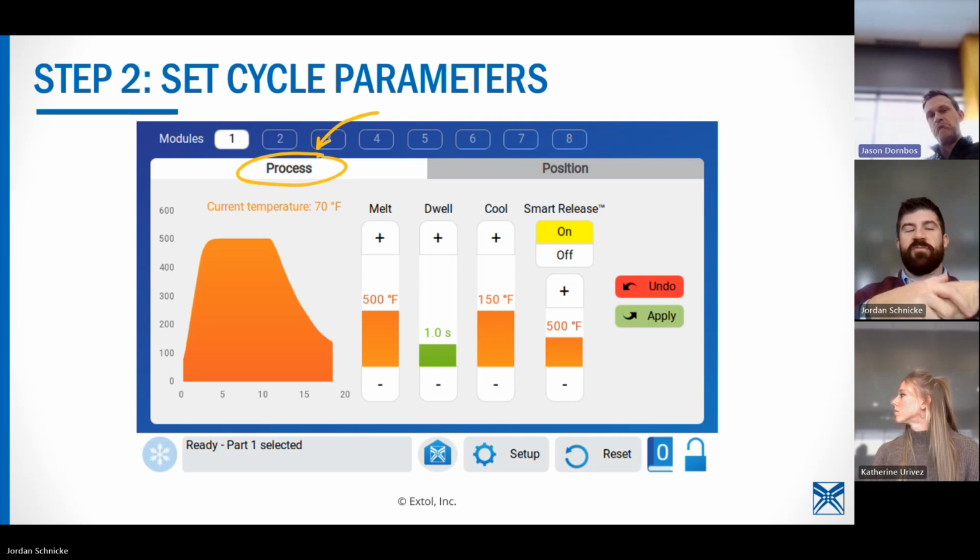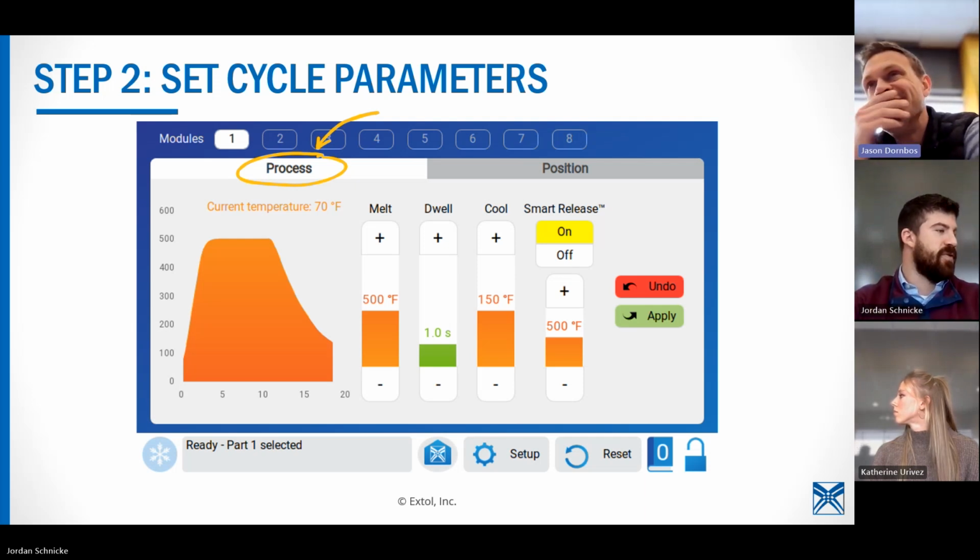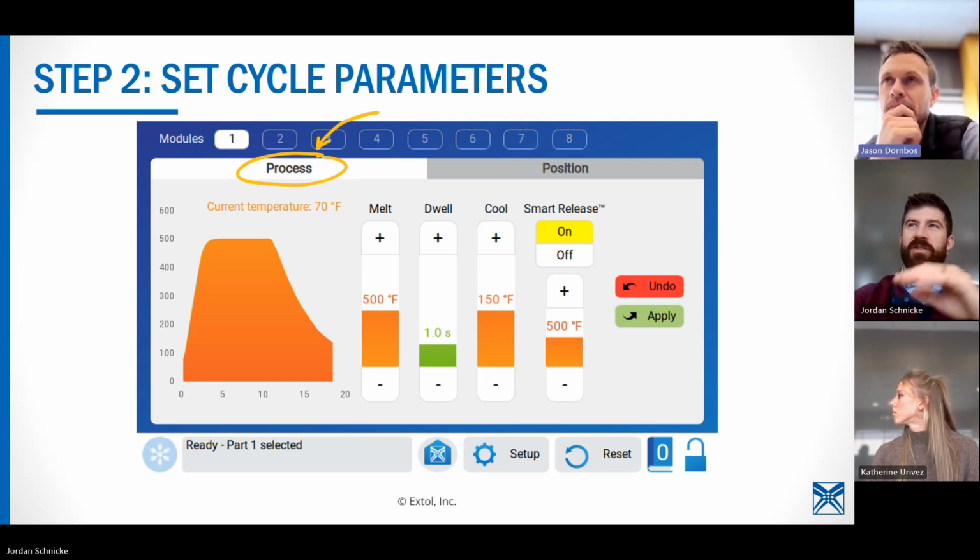remove that. The film thing is definitely, if you have an application that's been sticking, you might see some material buildup over time or a fogginess appearance. But more often than not, it's usually some sort of flash, whether it's an alignment issue or a mold issue. Flash is probably the biggest culprit, I would say.